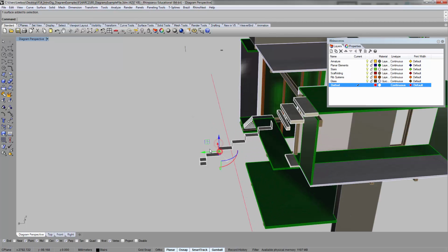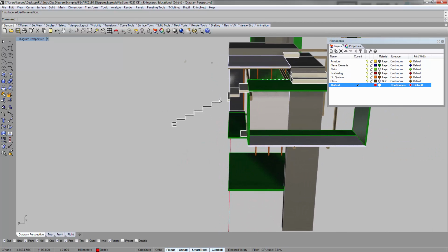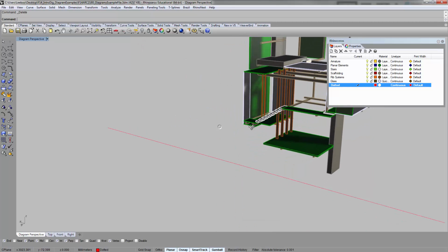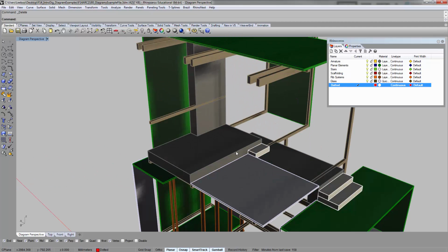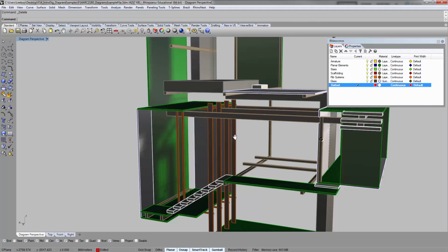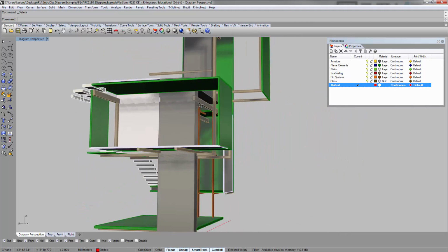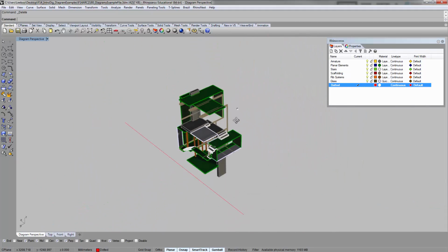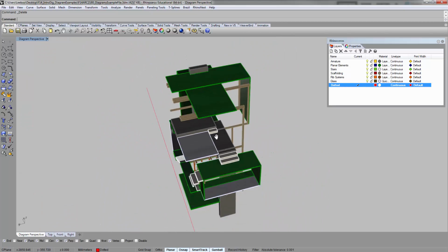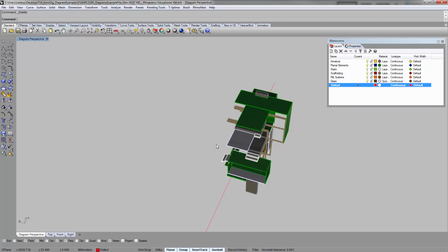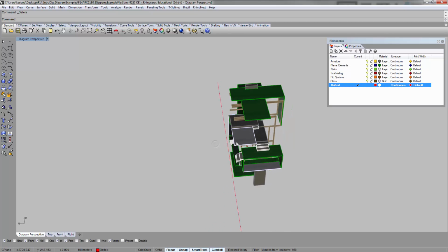So this version, sometimes it'll do some weird thing here and there. You might have to clean it out, but generally what it does is that after you do the cut, it self-heals the cutting planes, if it can, for the most part. All right, so that's kind of nifty or useful. That's just one version. So that's a wire cut command.